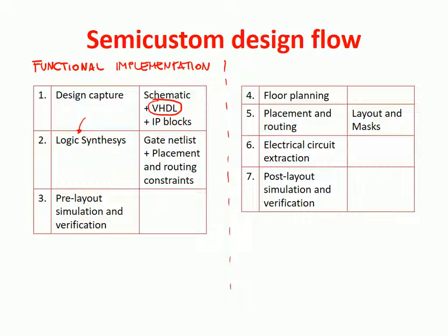The issue is essentially this. The length of an interconnection is associated to a delay of the interconnection. And of course, in the logic synthesis, there's a maximum delay associated to the interconnection from the output of a given gate to the input of another one. So there's a maximum delay for sending the signal from one gate to the other. And this maximum delay puts a limit on the maximum length of the interconnect. And this is the routing constraint. That of course has to be taken into account in the placement of the different blocks on the chip. So these are the placement and routing constraints.